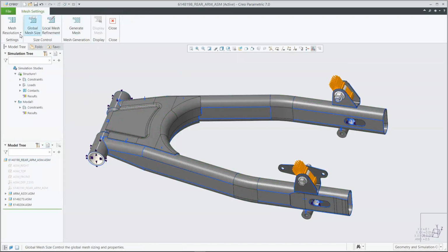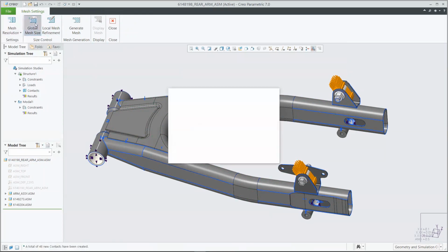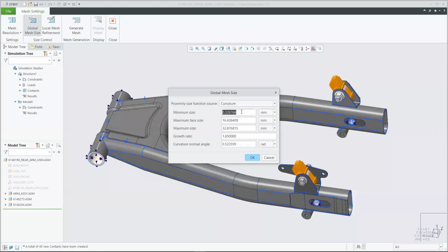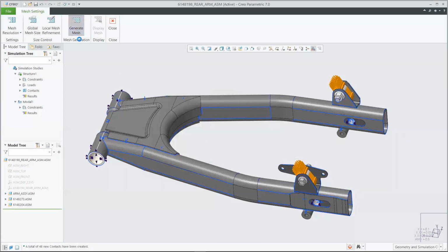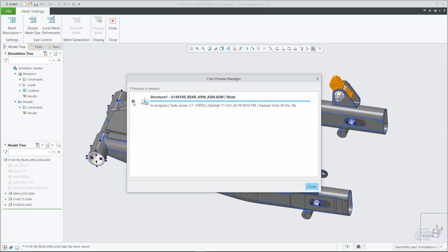For the mesh settings, this is where, right, if you want to just choose your resolution, great, run a low resolution, find any trouble spots, zoom into higher resolution if you want. You can also set your global mesh setting. So for your whole model, this global setting is going to say, all right, what's my minimum, my maximum? And you do get used to what you would use there, but you can always start off with just some generic mesh sizes or a mesh resolution, and then we'll see how the refining process goes on from there. We'll see that in a minute.